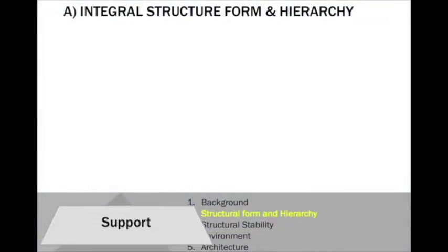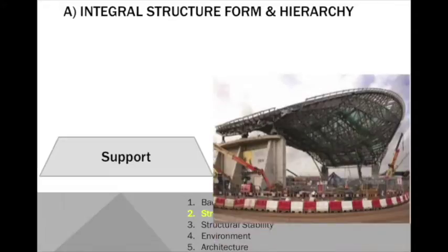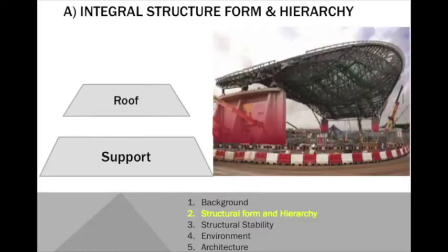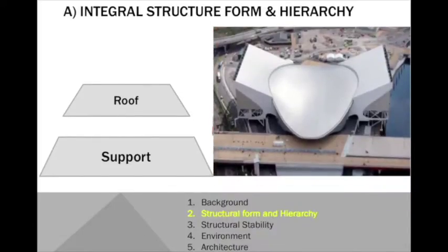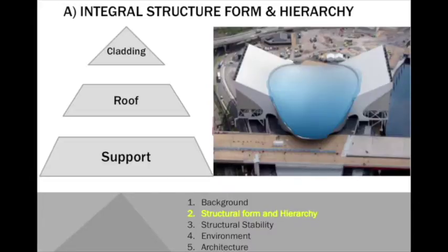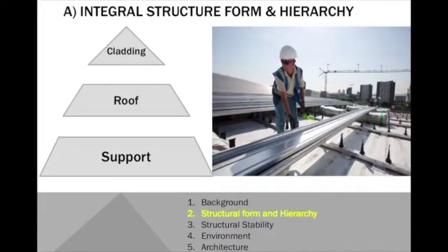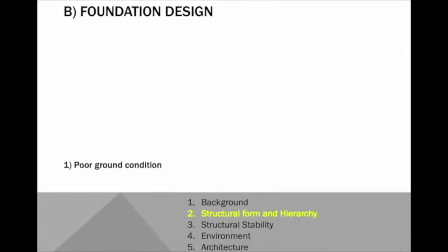The structural hierarchy can be divided into main, secondary, and tertiary. The main support system basically can be divided into two parts. The transport truss is supported by two reinforced concrete cores. The vent truss is supported by a reinforced concrete wall. For secondary, the architectural roof geometry was inspired by the flowing geometry of water in motion. For tertiary, the permanent roof is a warm roof construction created by insulated cladding on the top and timber cladding facing the pool tank.